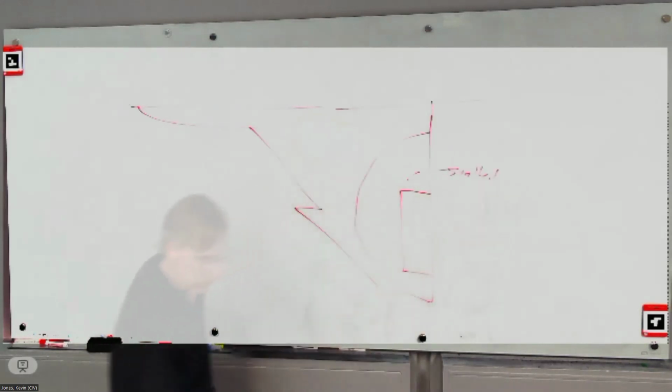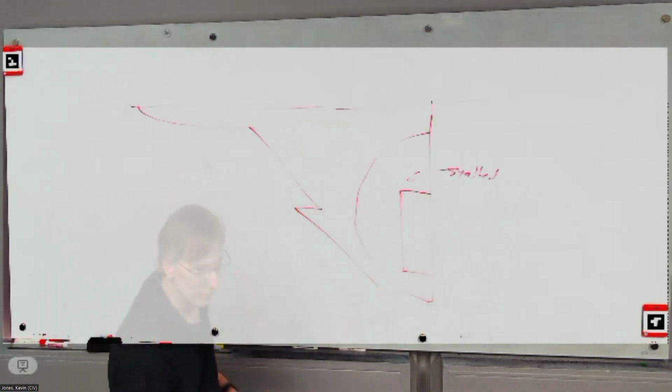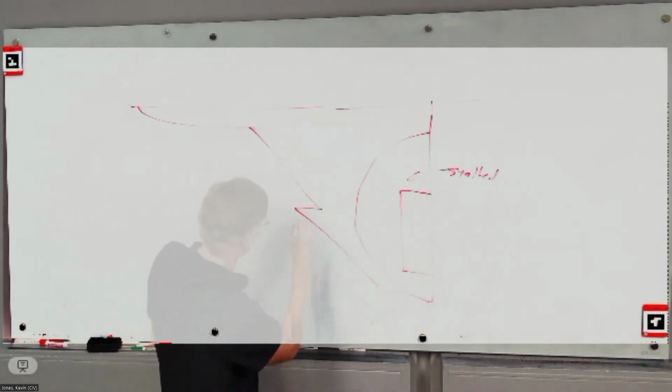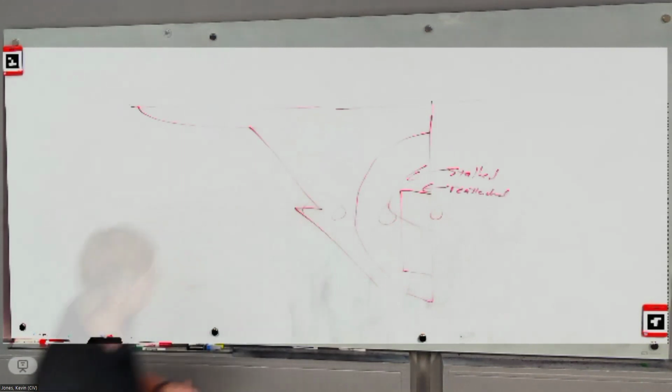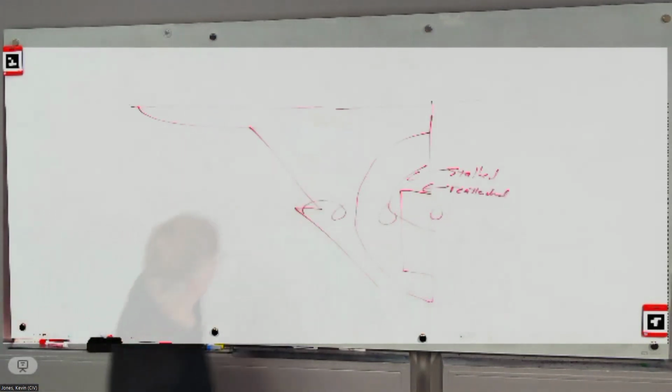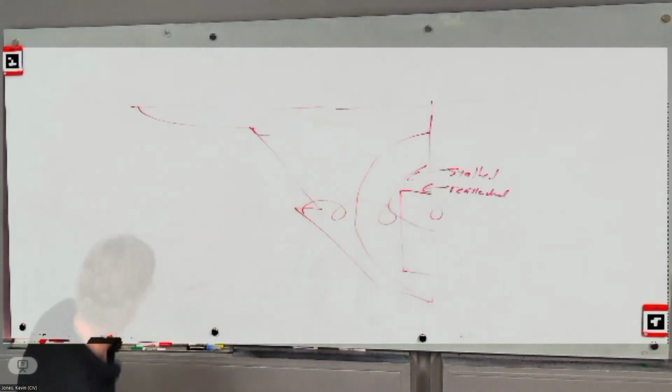And so the aileron became basically useless when the pilot was coming in for carrier landings. And lateral control became really hard. So the snag is another vortex generator. So it's a huge vortex. Now you have this pocket here that's attached, just enough to get use out of that aileron for the carrier landings. Yeah, and of course they've got a big giant vortex coming off of here as well, but it didn't reach out far enough to touch the ailerons.